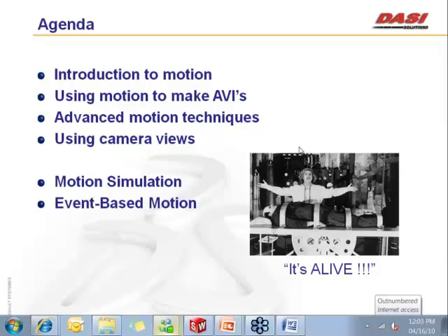Like I said, the first portion that I want to mention is SolidWorks Motion, and this is going to involve simply moving components inside your assembly documents, and also using the reference triad, which some of you may not know is available. And then that will lead into things like looking for a collision, using physical dynamics while moving those components. And another function that is kind of hidden out there is the record function, in case you want to record any of the motion that you're doing.